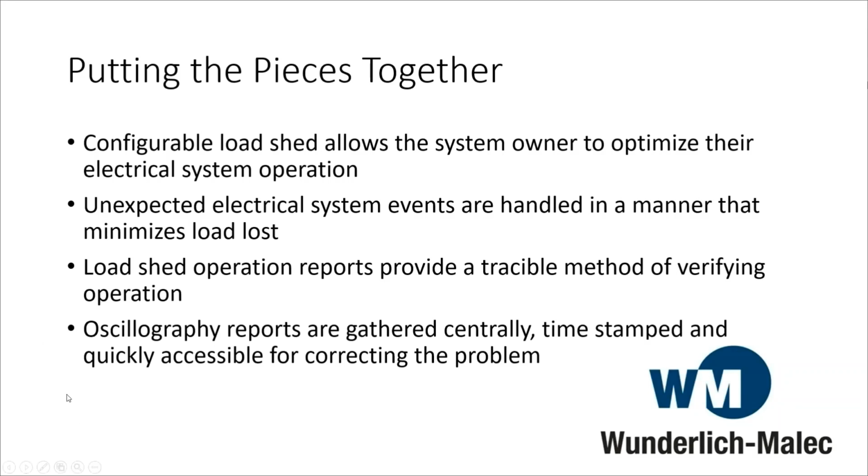Then you can drill right down into the electrical oscillography reports from the protection relays, and they're all there right at your SCADA terminal. They're time-stamped, and they're quickly accessible for troubleshooting and correcting the problem. So it's really the ultimate system for a high uptime microgrid or industrial or utility electrical system.